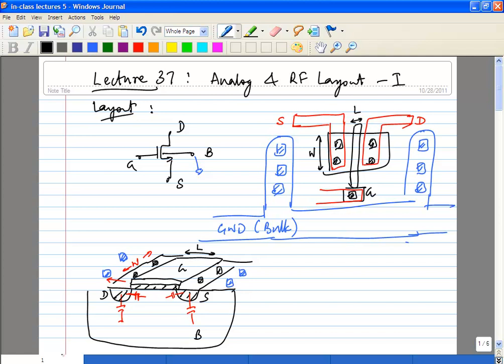You can make the same thing wider. The only thing you have to be careful about when you do all these things is parasitic capacitances. Typically these parasitic capacitances will be to the gate, or to adjacent lines, and these things may not be modeled very well. You have to be careful because even in your LPE step, layout parasitic extraction, there may be cases where capacitances on top of the transistor to the gate, there have been cases where people have got burnt.